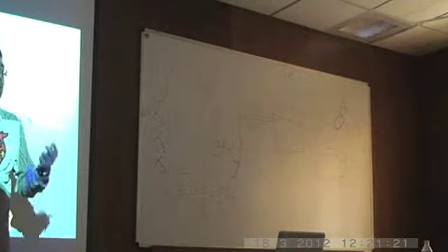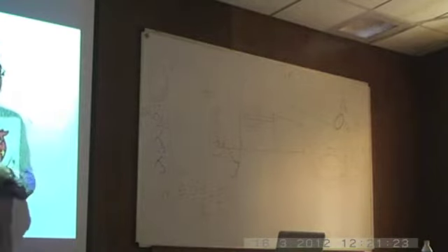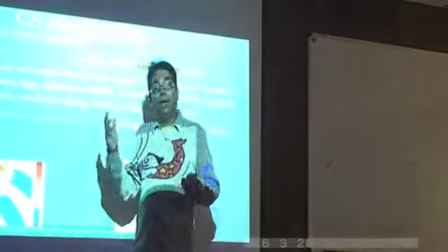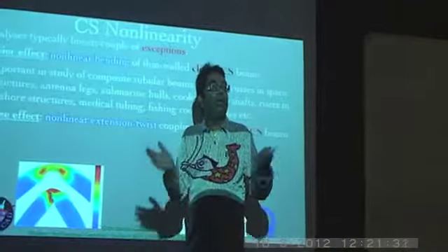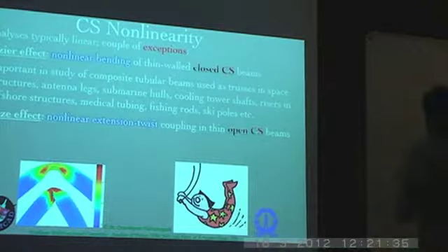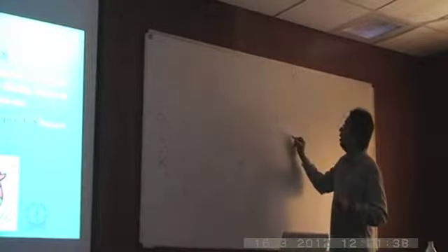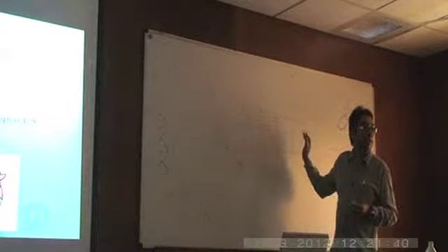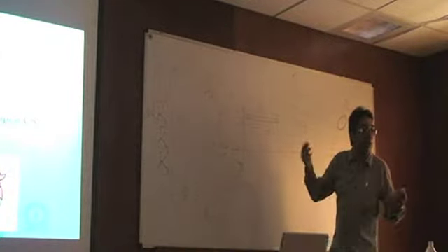But the primary thing that we are concerned about here is the fact that in the cross-section analysis there is a nonlinearity, or in other words, your stiffness matrix is something which is not made of constants, but is going to be a function of the 1D variables. But again, as I said, mathematically speaking, that can be put in a different way by instead of saying these are functions, you just add some terms which are non-quadratic as well. So that's another equivalent way of putting the same thing.